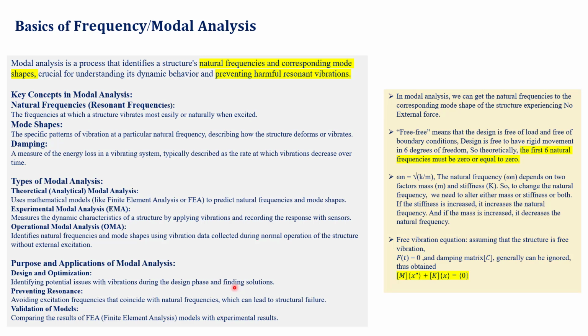Okay, while designing the components, let's say I have an assembly structure where I am going to mount an engine on the mounting structure. So I'll be using the fasteners, right? So in that design, if I see the fasteners have a natural frequency approximately equivalent to the engine, then definitely resonance will happen, and then the failure will happen, right? This is just a simple example, so you can even consider a lot of things. So this is what it is.